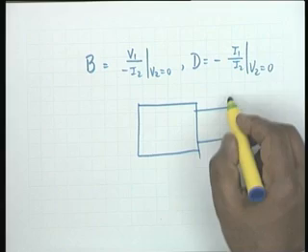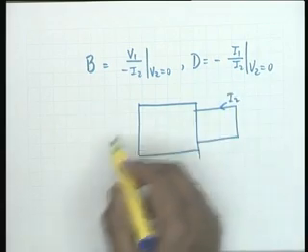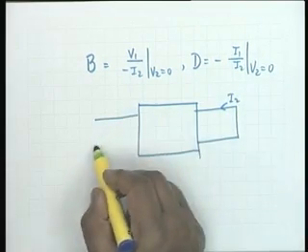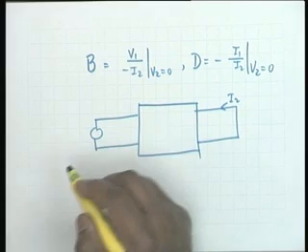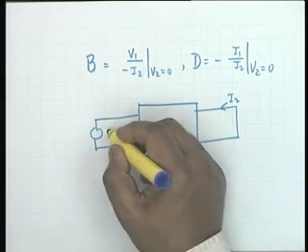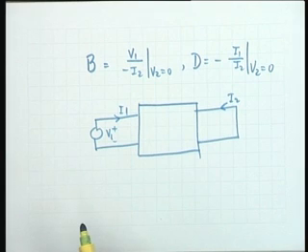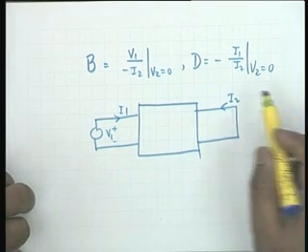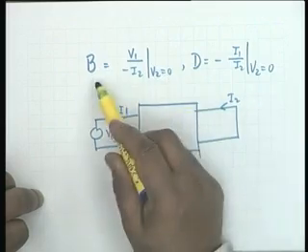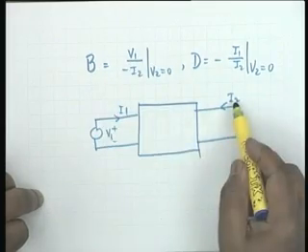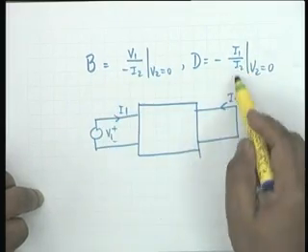V2 equal to 0 is this, the only thing you can measure is I2, and here you connect either a voltage source or a current source, but the net result is that the voltages and currents are V1 and I1. And now what I have to do is find V1 by minus I2 or I1 by minus I2.